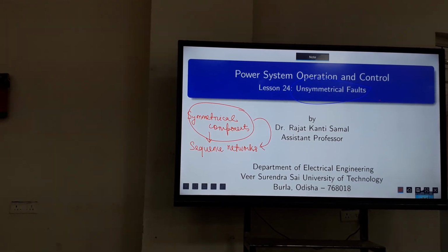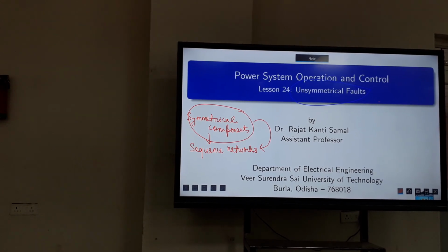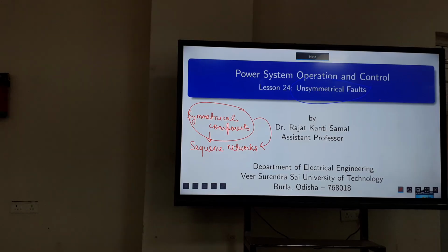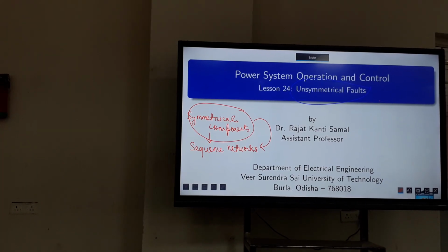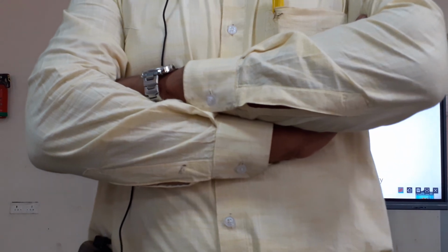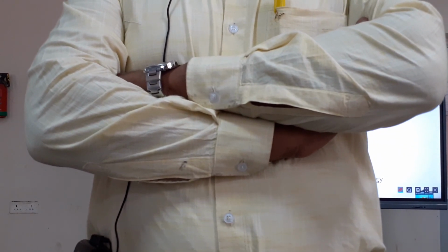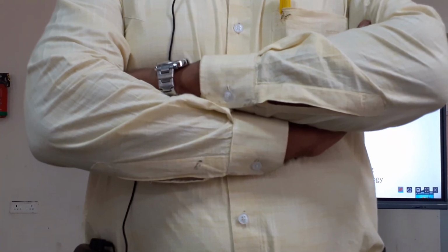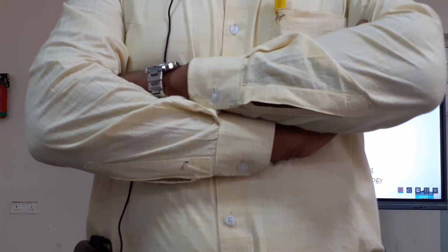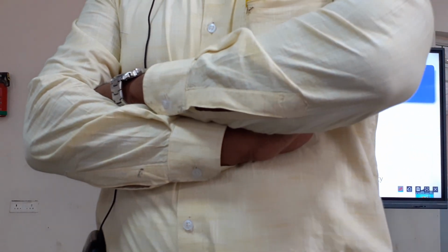Now, the interesting case is the transformer. For the transformer, the positive and negative sequence reactances are nothing but the leakage reactance. Why? Leakage reactance means the transformer reactance. So positive and negative are both the same as the transformer reactance. Why? For generators it is different, but for transformers it is the same. Because it is not a rotary machine.